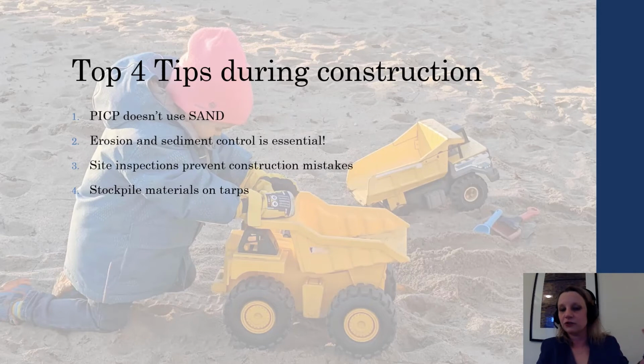If we have construction runoff depositing silt and clay and dirt where a permeable pavement is going to be constructed, or on the surface or on the aggregates as it's being installed, this is going to mean that we don't get the high infiltration capacity that we want from day one. So making sure that sediment erosion control is done well is absolutely key. The best way to do this is, of course, through site inspections, preventing construction mistakes, making corrections before things proceed too far and they become expensive to repair.